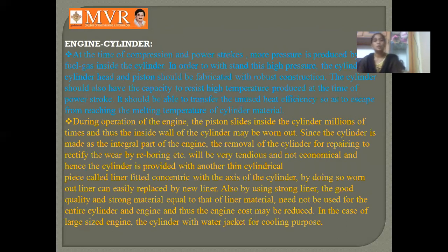At the time of compression and power stroke in the engine cylinder, high pressure is produced by the fuel gas inside the cylinder. In order to withstand this high pressure, the cylinder head and piston should be fabricated with strong construction. It should be able to transfer the unused heat efficiently so as to avoid reaching the melting temperature of the cylinder material.